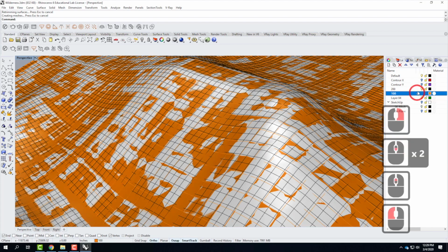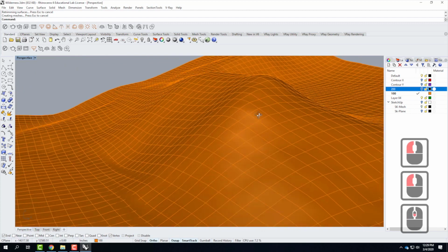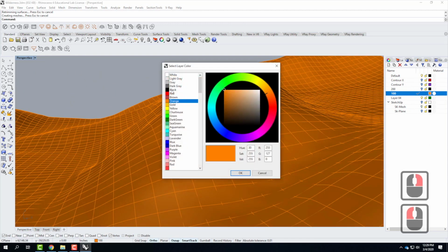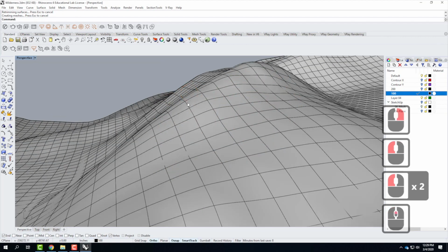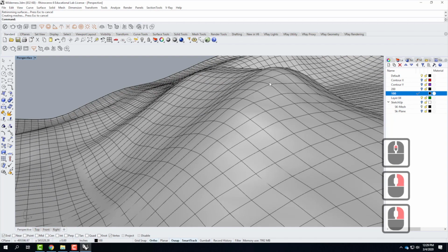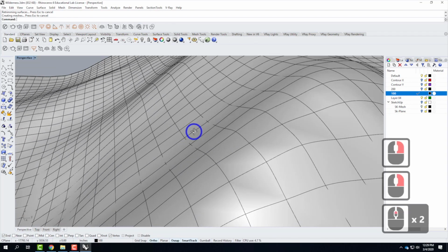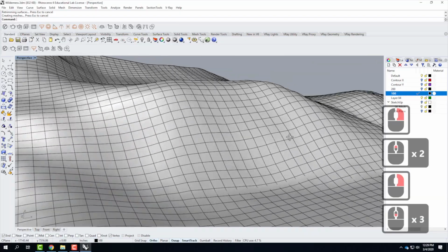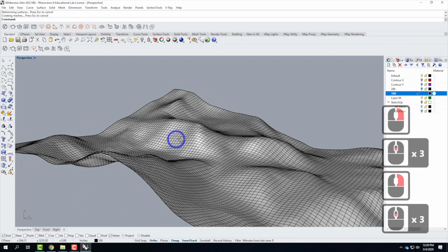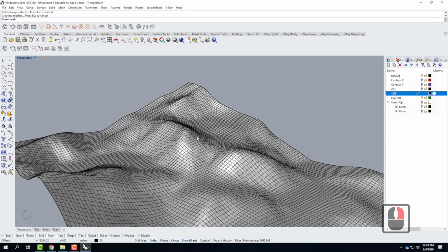If I turn off the 200 and we look at those ridges that we were doing, you guys should be able to see this okay still on the screen. Let me change it back to some of the black; usually just shows it better on the screen. You can see that little ridge that goes along here, it's gotten a lot smoother. Right up here at the top, that's starting to get a lot smoother. So that value might be a pretty good approximation of a nice smooth set of terrain. So that might be the right amount of rebuild.